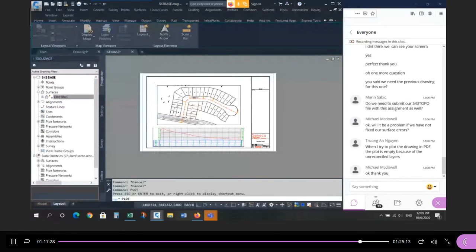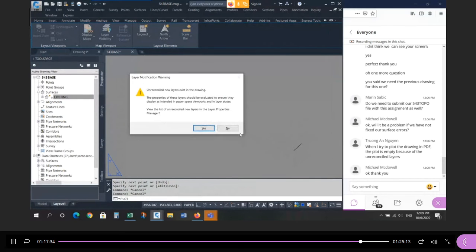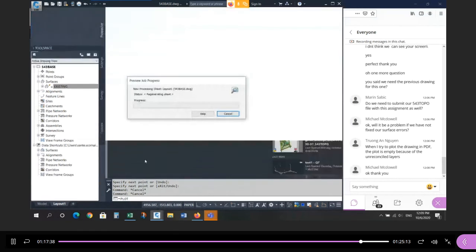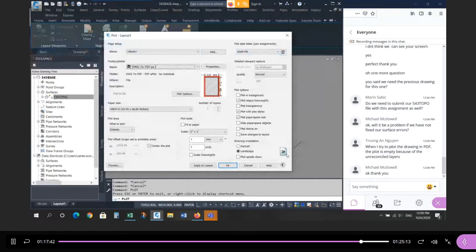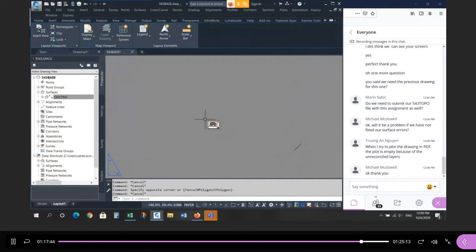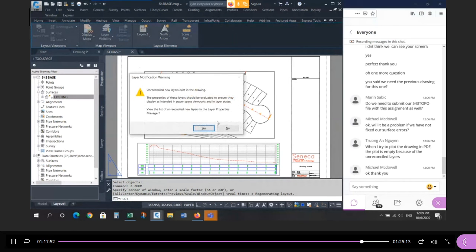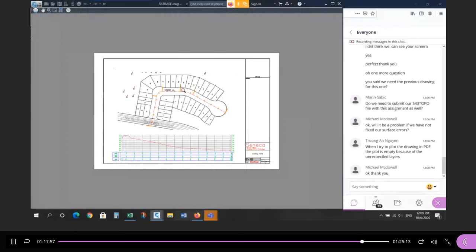If you don't see stuff, if you zoom extents, and you have some line out here, and you go to plot and you say preview, because this says extents, it's going to look like this. It's a problem. If you have what I call space junk, something out here outside the frame of the drawing, you could end up with that effect. So I want you to erase anything that's out here. If you zoom extents and it fills the window, when you go to plot, it should fill the sheet.